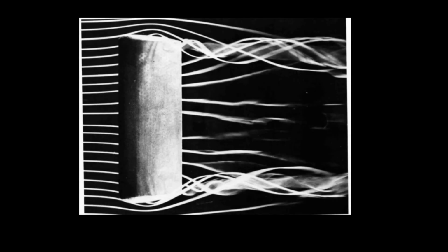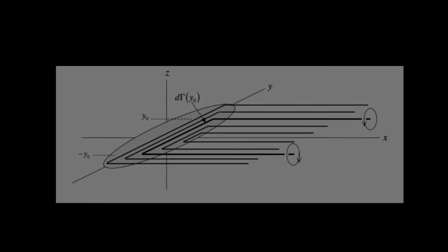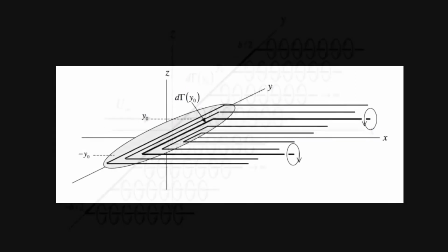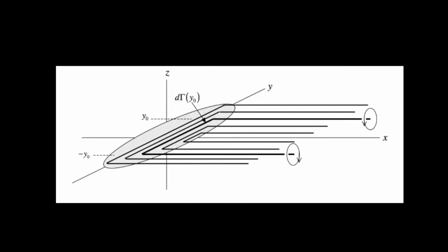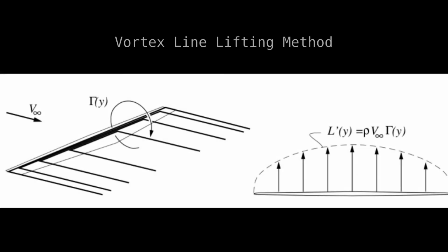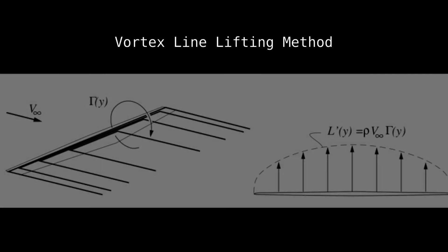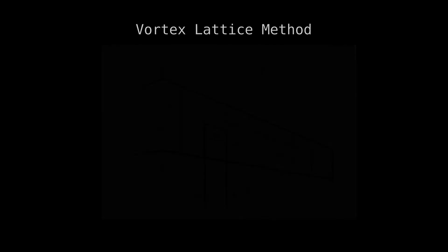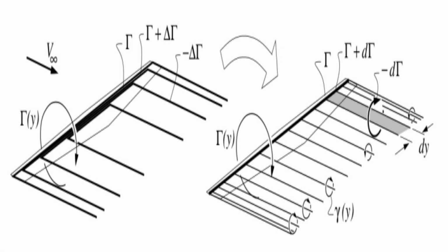The finite wing theory is again a step beyond the 2D wing theory, in that circulation is still fundamental to the concept and the vorticity forms a trailing vortex sheet. The circulation is calculated along each of these horseshoe lines. There are a couple of variations of this method, Prandtl lifting line and the vortex lattice method. In both cases, when the vortex is perpendicular to the chord length, it is inducing a force on the surface. However, when the vortex is running in line, it is not. This is an important concept.